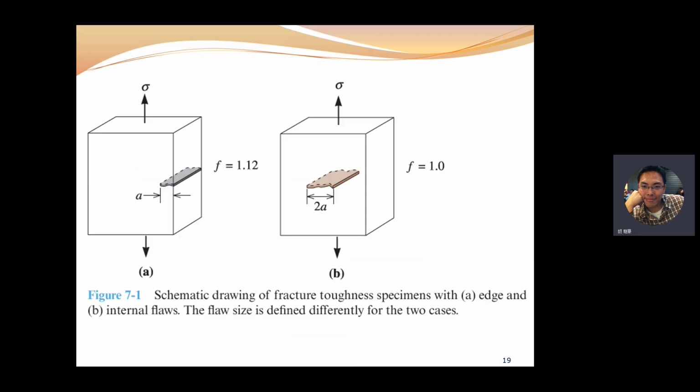So there are two cases. If the crack is on the edge or on the surface, and it's a semi-infinite plate, the geometric factor equals 1.12.